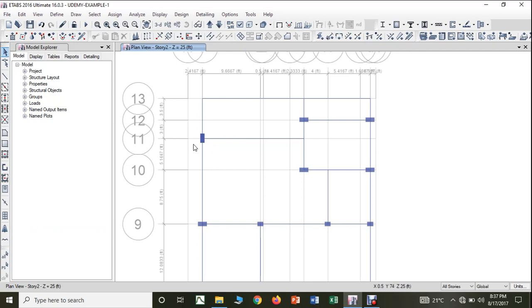So now this is the most suitable orientation, right? As I already told, there will not be any eccentricity. This wall and this wall will be in continuation with this column, and since more loads are coming from these two beams, they are along with this. So it can easily come and sit at the center of the beam. So no issues with this column, the orientation is changed.